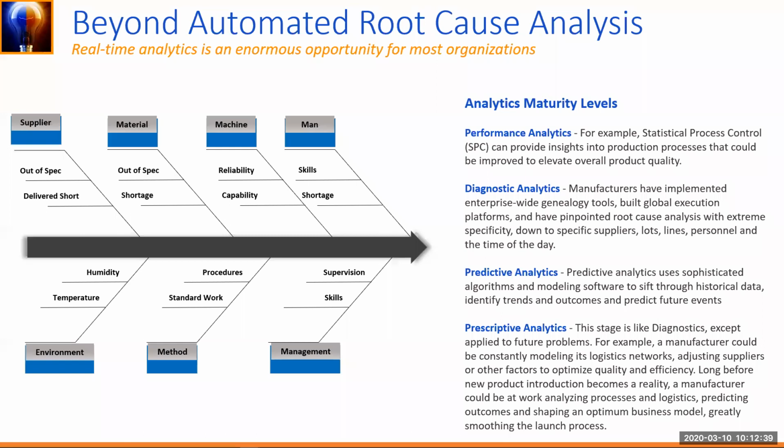Prescriptive analytics are basically taking the next step. With predictive, we're saying when something is going to occur. Prescriptive analytics actually then close the loop and control the process itself, so that you take that next step out of the hands of the humans running the process. So here, for instance, in a humid environment, different powders that you're loading into a product may change behaviors, and so you can actually change the mix in the loading machine based on the environmental conditions. And we've done that in plants as well.